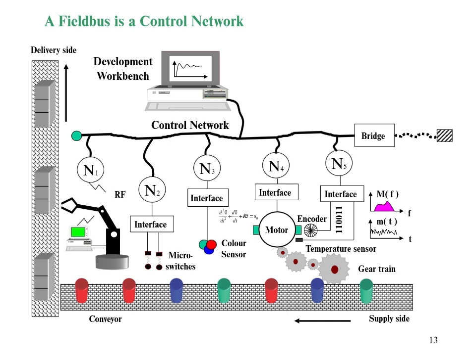Let me talk about the Fieldbus technology. A Fieldbus technology is actually a control networking system using which you can implement a distributed control. What is the meaning of distributed control? It's not centralized control, meaning that all the microcontrollers are connected into a network. In this application, this is a packaging line application. It has a robot, a conveyor belt, and a motor, and also sensors. All these sensors and motors are called actuators. Sensors and actuators are connected into a single network, and it's called Fieldbus.